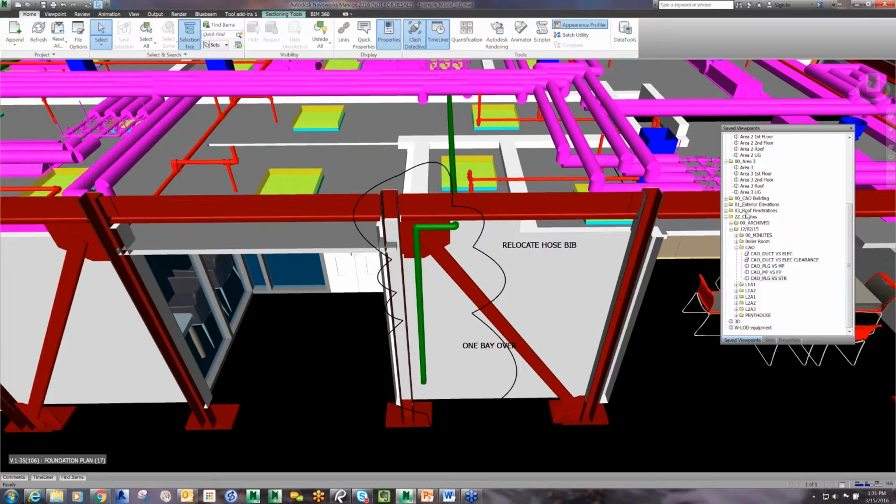And then we'll usually move into new clashes and run the Clash Detective and go through and identify any new clashes that have cropped up from the submissions from that week. So hopefully, once we go through this for one area, we'll have a sign off, which basically says that there's no meaningful clashes left in that area of the model.